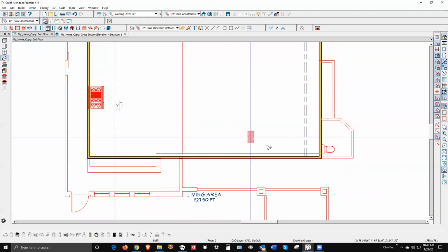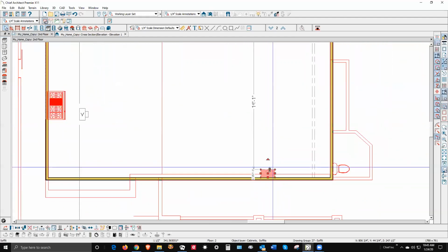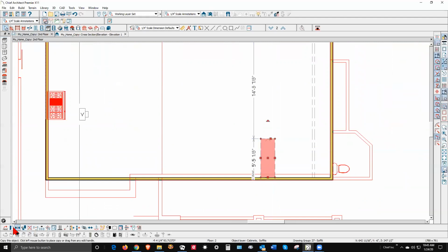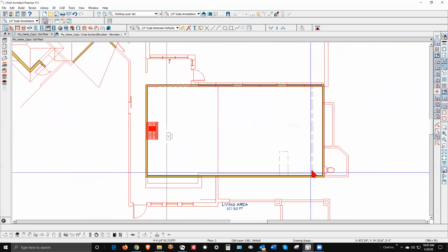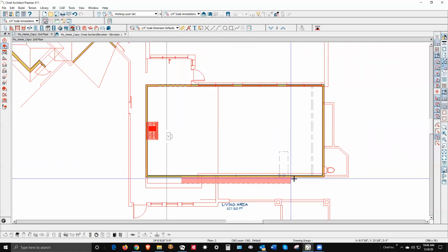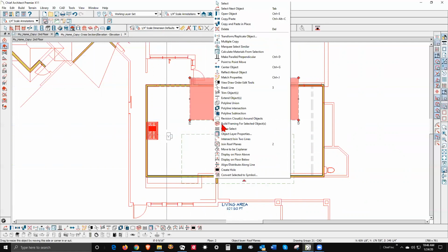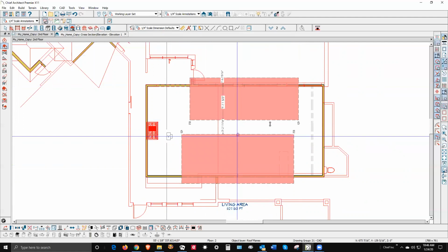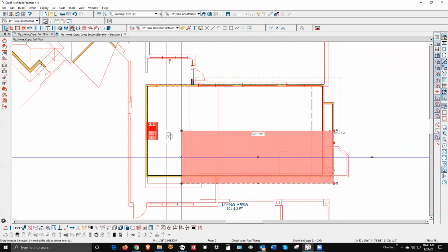Have the soffit pointing in the direction you want it to slant. I'm just going to extend it. And I want a, I don't want to place it, oh, okay. I have to have, I think what I'm going to have to do is put a roof on it here. I'm just going to put a gable roof on it for now. I'm going to use your presettings and assume that you set the roof to where you want it. And join that into a gable and then just go over the top of this room. I don't care about the overhang. I'll leave that to you to adjust.